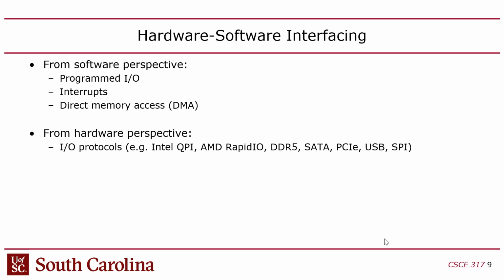It's just a hardware abstraction layer, a set of libraries. It's not something that gives you a shell prompt. There's no shell prompt. There's no interactivity with a terminal with a real-time operating system. You essentially statically compile your code into it, and then it just acts as a runtime environment that manages the execution. But it doesn't give you a bash prompt, right? So if you ever see a prompt on an operating system, it's not a real-time operating system.